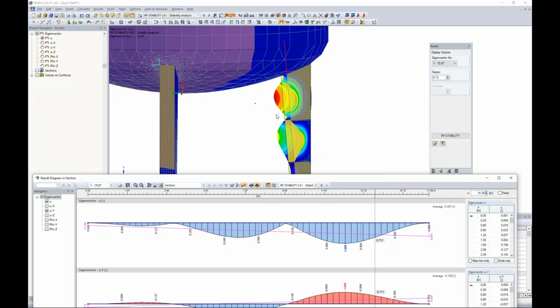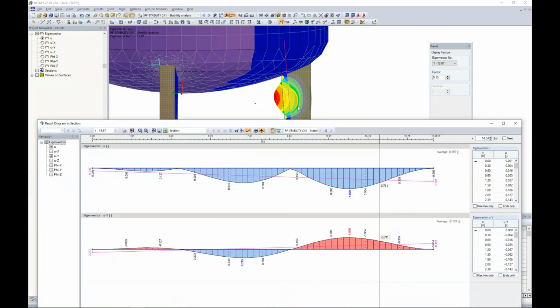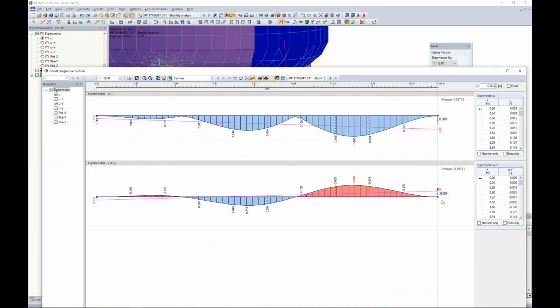This comes from the AISC Code of Standard Practice, in particular Section 7.13.1, which discusses misalignment of members and surfaces. These tolerances can be less than L over 500, where L is the distance between working points. Keep in mind that L is not the distance between the start of my surface and the end of my surface, but rather I want to use my working points, where I see my inflection points. Looking at the general buckling view here, the first inflection point takes place at about 10 inches, and then I scroll over to the end at 17 inches. This would be my working point distance of about 7 inches in total.